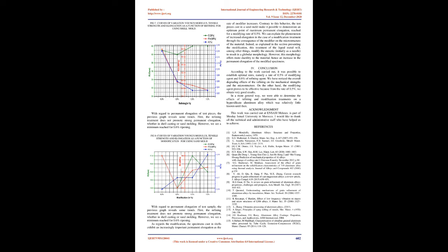The blue tables serve as references, that is to say, they indicate the characteristics of the test pieces without treatment. We recall that A % represents the permanent elongation of the test piece under the stress Rm. To compare these results and to be able to analyze them, let us draw up the following graphs, that is to say, Young's modulus, E, GPa. Tensile strength according to the different treatment rates, refining and modification, Rm, MPa.